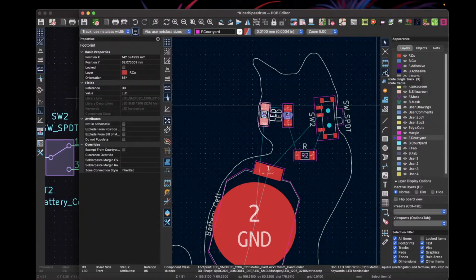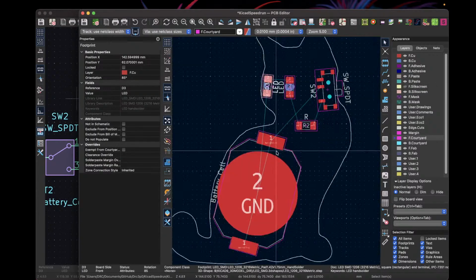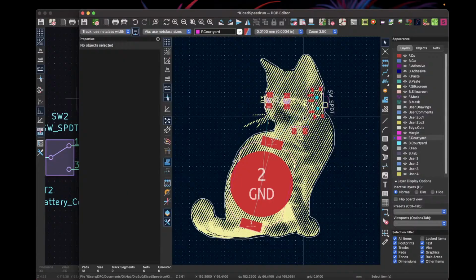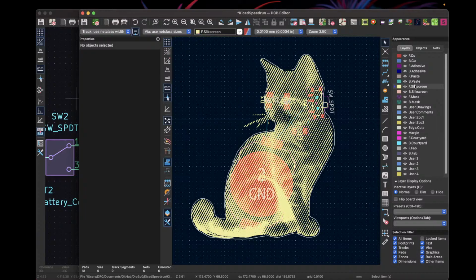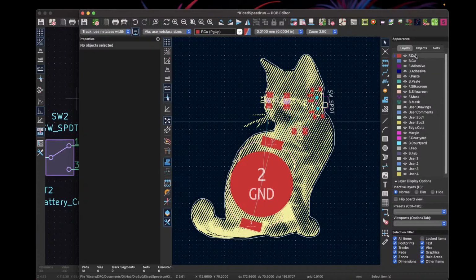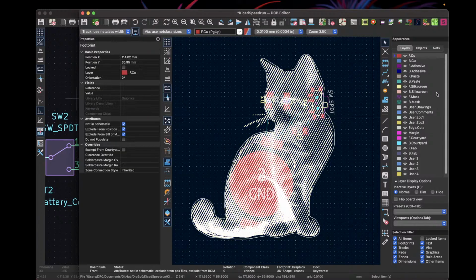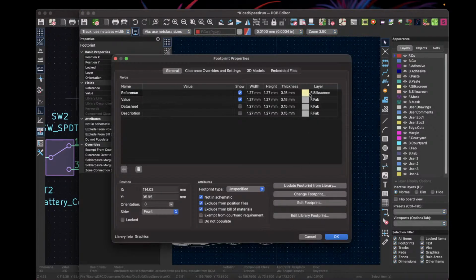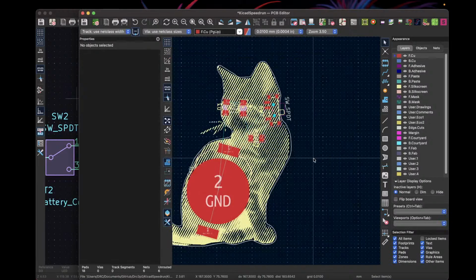And so this is the wire button here. Oh, one thing I just remembered. Right now we have this front silkscreen layer. But we also have these parts on the front layer. So we don't want the silkscreen art layer on the same side as that. So before I forget, we are going to change that. Because it's a weird graphic, I don't know. See if this will let me do it here. I'm gonna try to swap it to the back silkscreen layer.